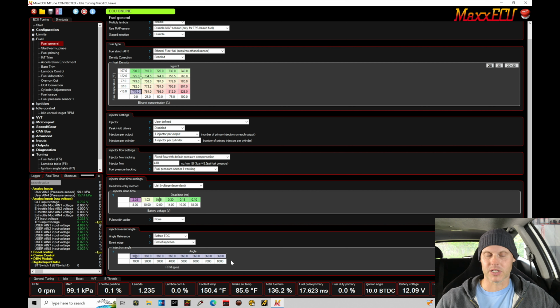We have them at 360. That's a good starting point for pretty much any piston engine, 360 degrees across the whole table. That'll get you going. That'll get you probably about 90% of the way, and then we can further tweak and adjust those values, again, based on looking at some trial and error, and I'll explain how that's gonna go at the end of the tutorial.